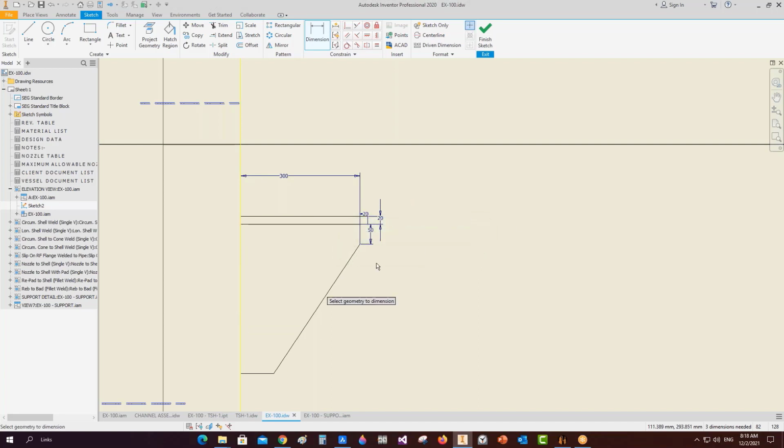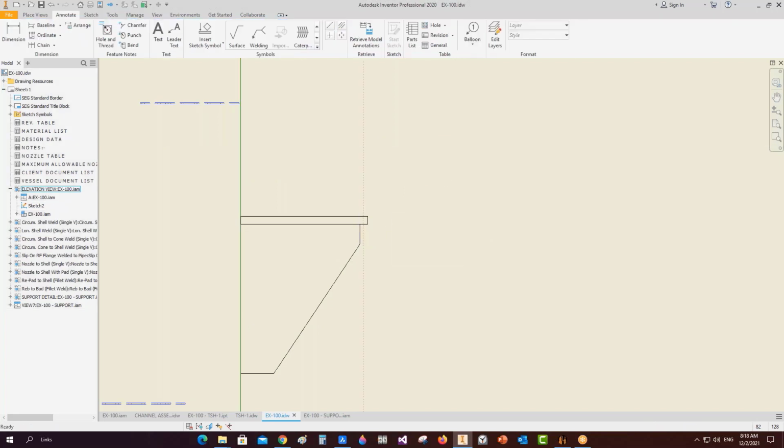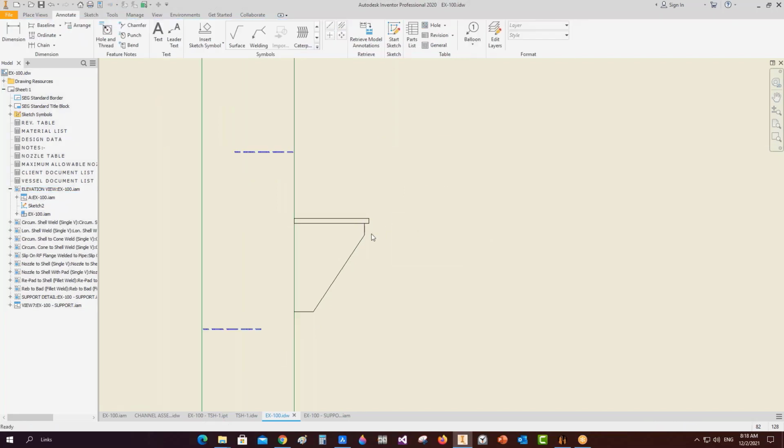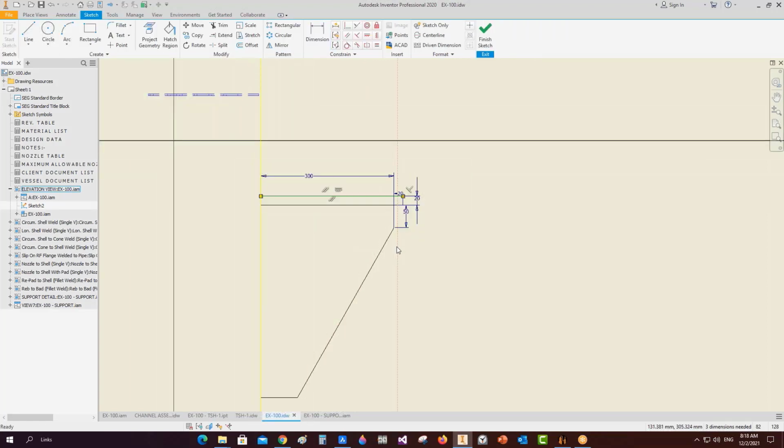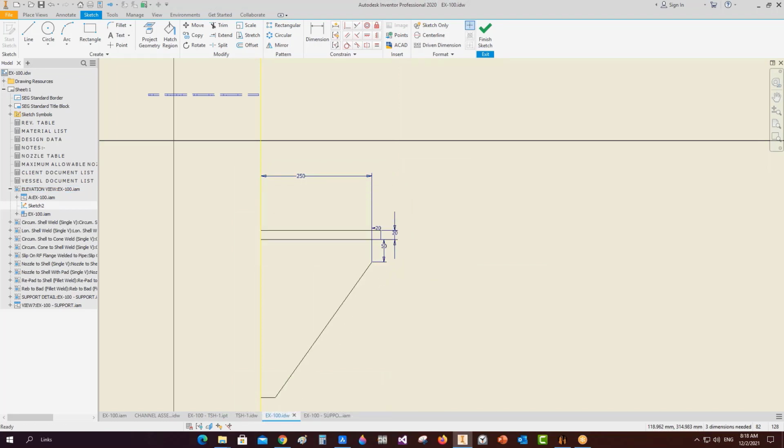For example, it's a parametric sketch. In AutoCAD, you draw each line separately, but here, if you move one line, they are attached to each other. Those dimensions are already controlled. Any time you would like to modify, it will change automatically. But in AutoCAD, you should make it a parametric sketch. Automatically here will be a parametric sketch. I think you know what I mean.